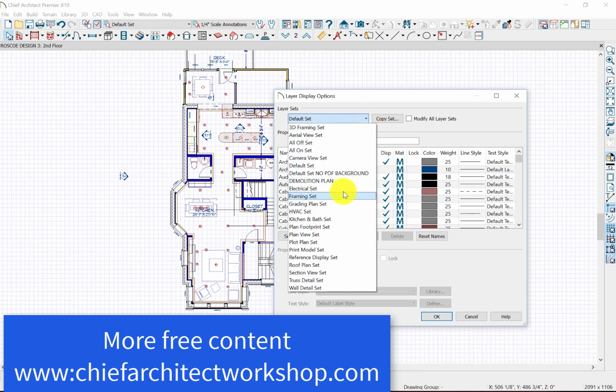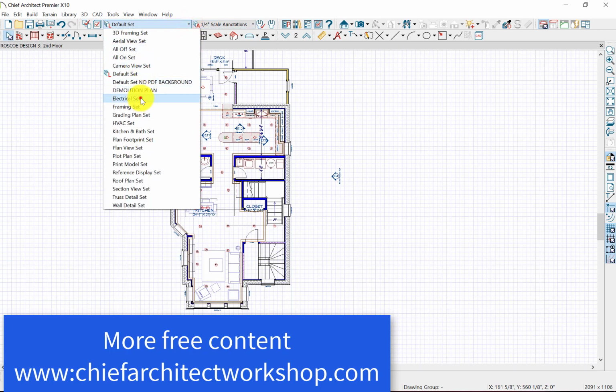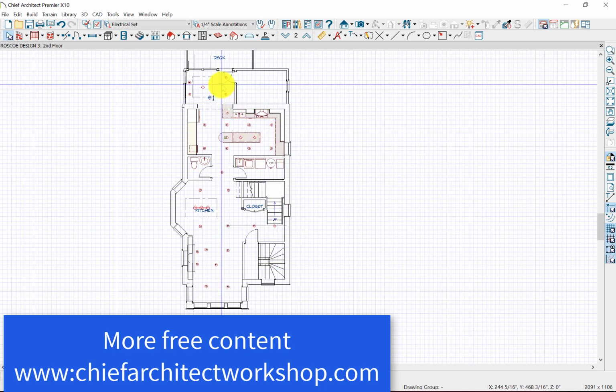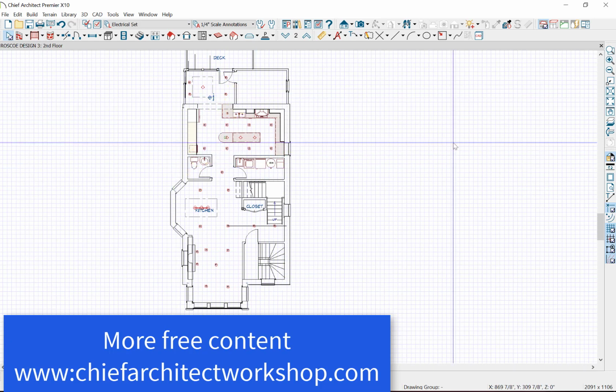But so this is what's displayed in the default set, and then you can change that default set to the electrical set. Hit OK, and let's go over to the electrical set. That will just display the electrical items. And this is a design set, so there's no switches. There are no switching located here. This is just to study the lighting and see how that looks for the design set.